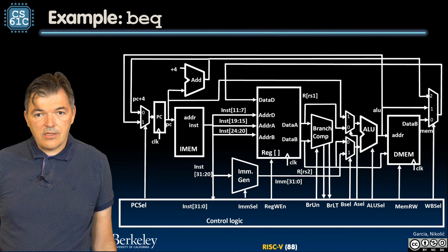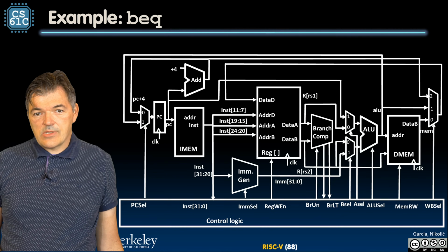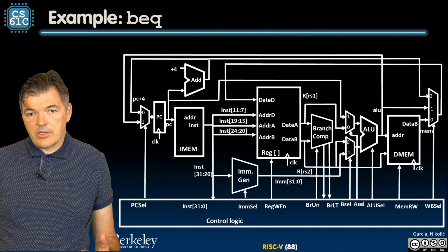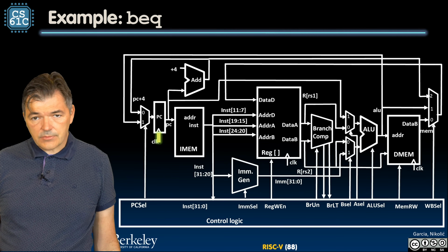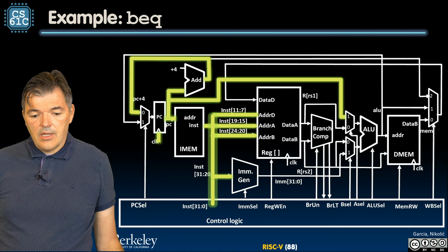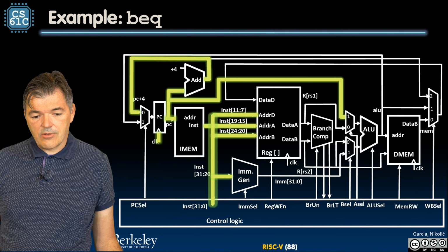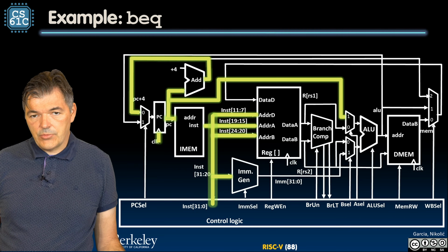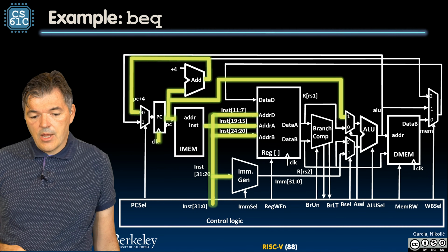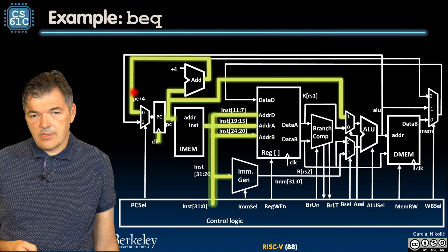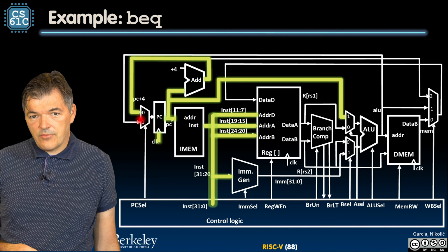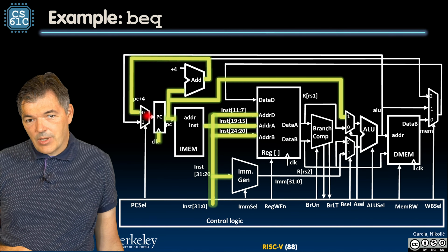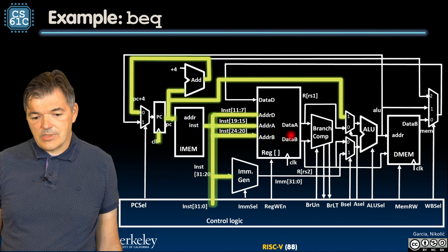Let's take a look at another instruction that we visited early on, and we are going to do that a little bit faster this time. This is branch if equal instruction. So it also starts on a clock tick. Multiple things happen concurrently. We increment the PC to a value PC +4, but keep in mind that this is not going to be ready for writing into a program counter anytime soon, because that will be about the last thing that happens in the branch.